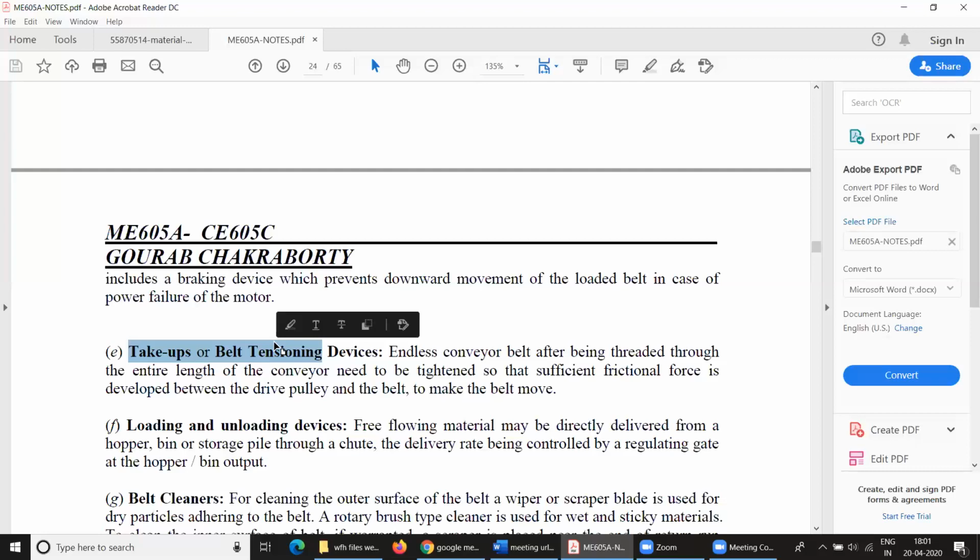The belt carrying material must be flat passing over a slider plate at the plow to allow close contact between the belt and rubber tipped plate. The plow is pivoted so that the position is adjusted above the belt to control the material being discharged. This is the loading and unloading devices part I am explaining.